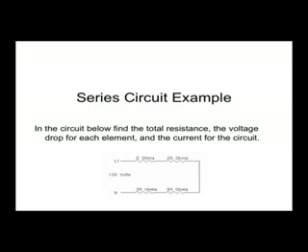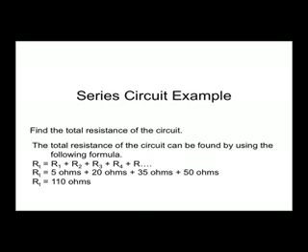The voltage in a series circuit is completely used by all the loads in the circuit. The voltage of the series circuit may change through each load. That's why we don't have very many series circuits in HVAC for loads. The change is called voltage drop. The voltage drop across each load is the amount of voltage used or lost through any load or conductor in the process of moving the current. The sum of the voltage drops of any part of a series circuit is equal to the voltage being applied to the circuit. The voltage drops all add up.